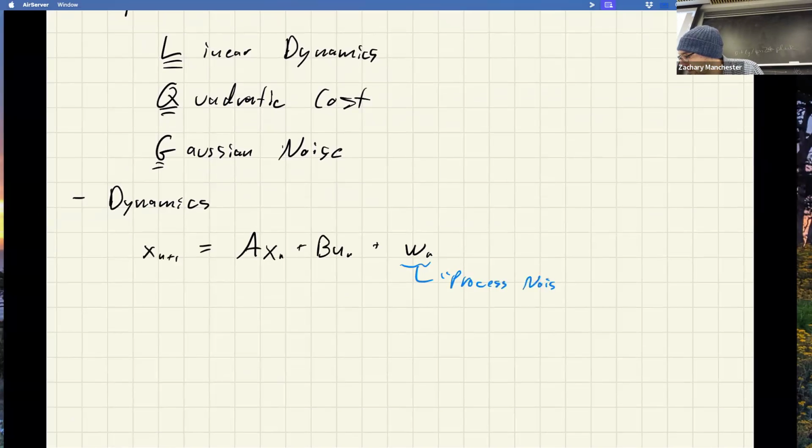So we're basically assuming that the dynamics have this deterministic part, which is what we're used to, plus they're also driven by a noise input. The idea is that every time step k, you're going to draw a w from a Gaussian distribution and add that on to the dynamics. So the dynamics are random, they're stochastic, right?